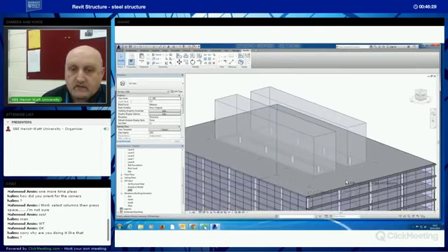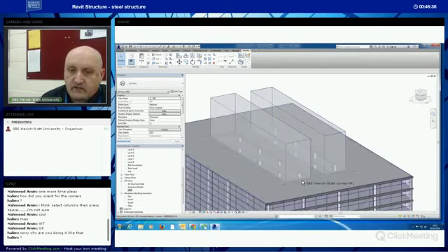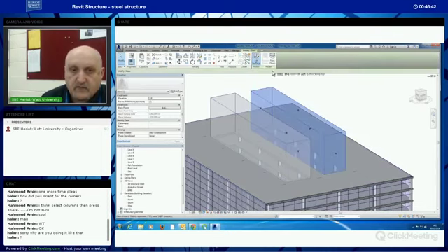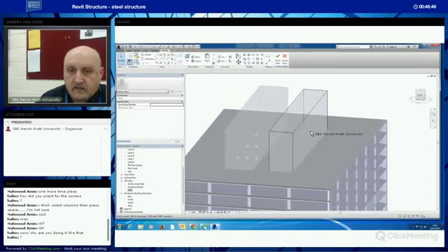Okay? I don't think it matters that much. Perfectly acceptable for a curtain wall to be suspended at the floor edge. Clearly here it won't be. Now I'm going to select this one here. I'm going to edit it in place. I can select edges, faces, or corners. It's the bottom face I want, so it's that one.